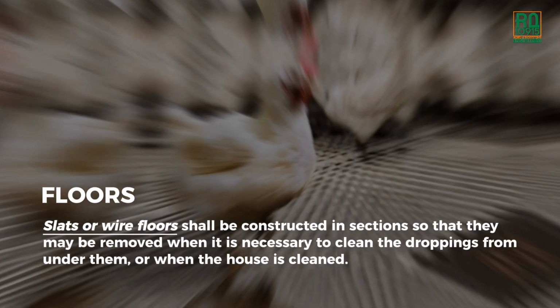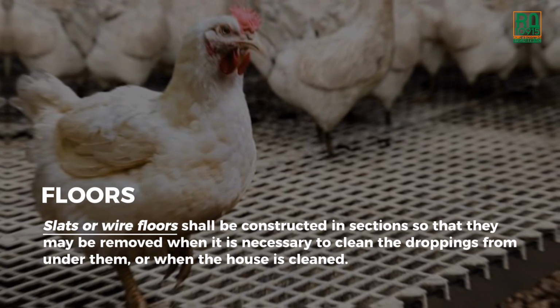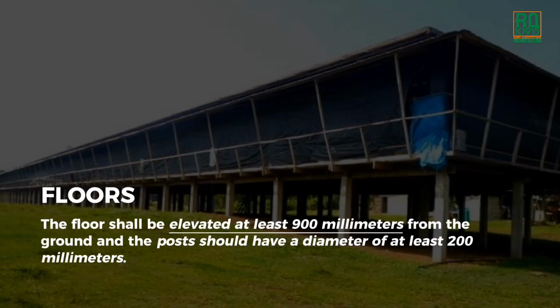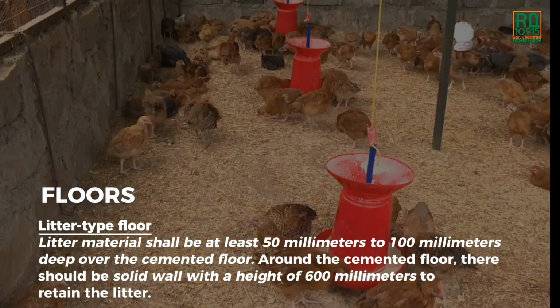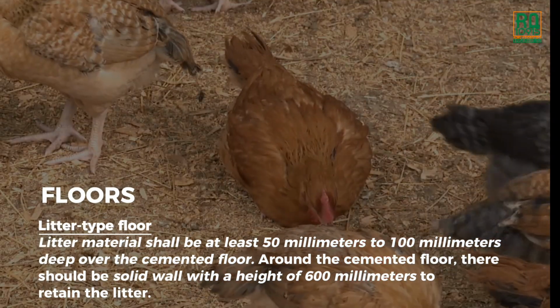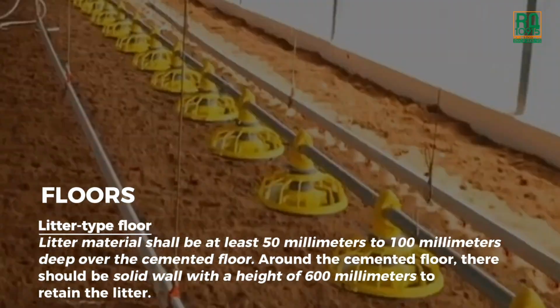Slats or wire floors shall be constructed in sections so that they may be removed when it is necessary to clean the droppings from under them, or when the house is cleaned. The floor shall be elevated at least 900 mm from the ground and the posts should have a diameter of at least 200 mm. Litter type floor. Litter material shall be at least 50 mm to 100 mm deep over the cemented floor. Around the cemented floor, there should be solid wall with a height of 600 mm to retain the litter.